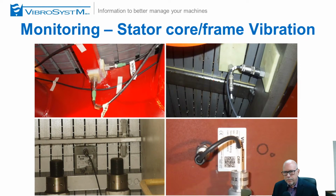Now, in some cases, people also have issues with stator core and/or stator frame vibration, and then there's a series of sensors that can be used for that type of monitoring. As you can see in the picture here, we're talking about piezoelectric accelerometers. Some are installed on the core, some on the key bars, some may be installed on the ribs, some on the frame. The idea in general is to see if amplitudes are high first and foremost, and then to look at the frequency content to see if it's pure 100 or 120 hertz, or if there are other frequencies present that may indicate a secondary problem.